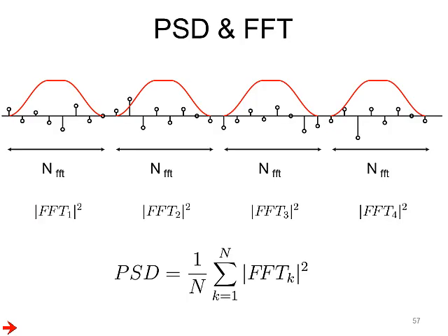Another common source of doubt is the difference between the power spectral density and the FFT. I'd just like to quickly mention that if you had a long record length, say of 4 NFFT points, one way of computing the power spectral density would be to divide this record length into multiple chunks, each with a record length of NFFT, compute the magnitude squared of the FFTs of each of these chunks, and simply average them.